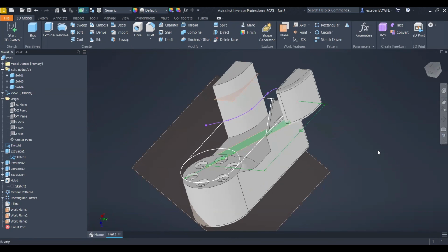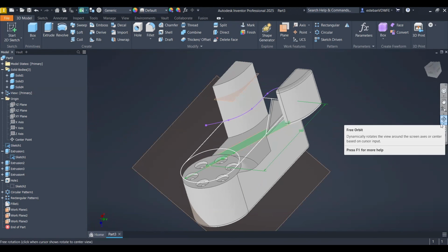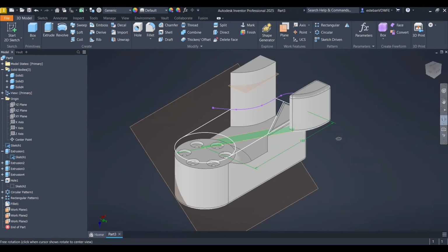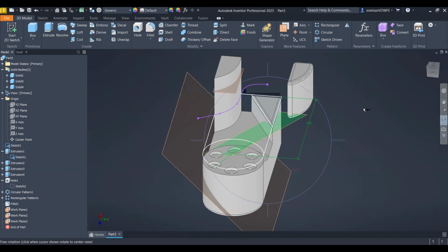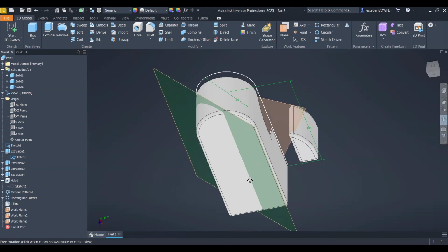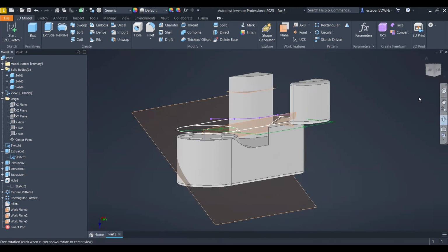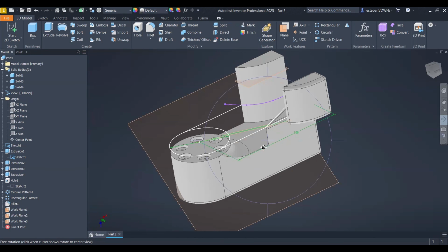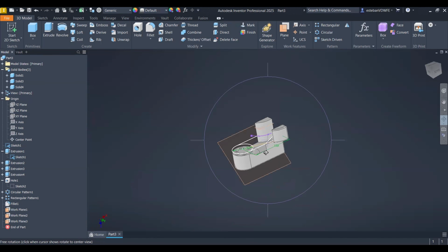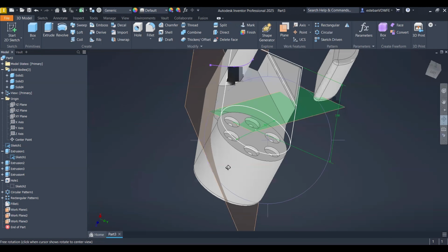Okay, if you use the orbit option, there are 3 types of orbit. So one is constraint, and you can select, it's like constrained to a plane, so it doesn't move that easy. I used to use orbit, just orbit, and you can, especially on assemblies, it's really useful, but you can redefine the rotation point by clicking.